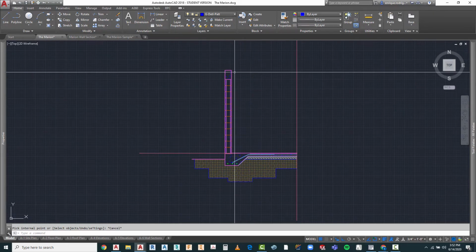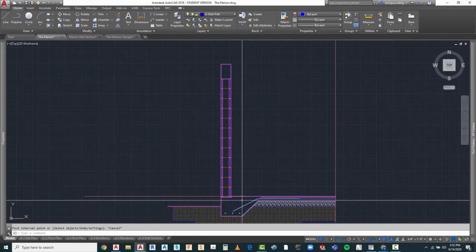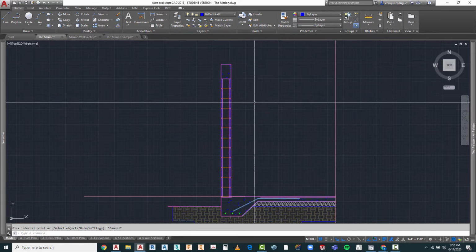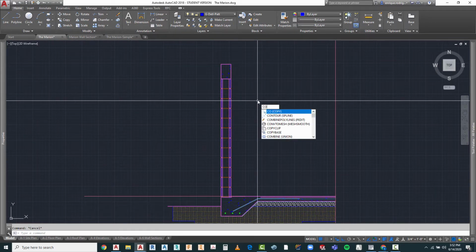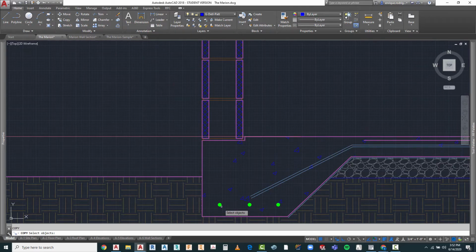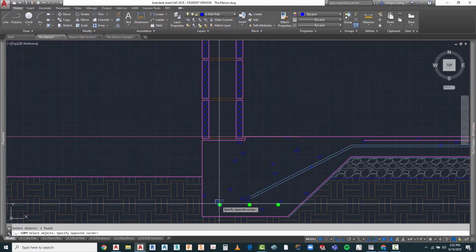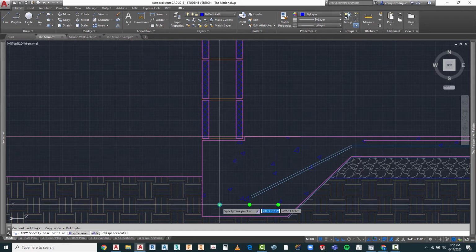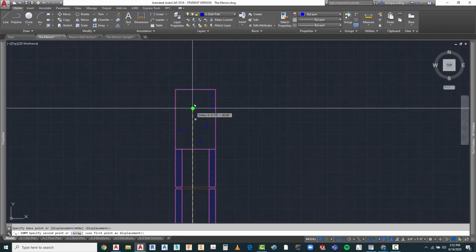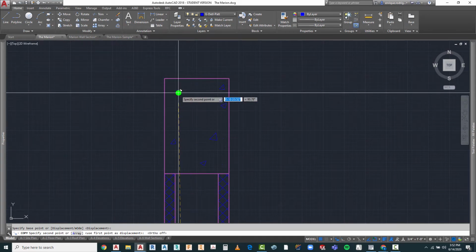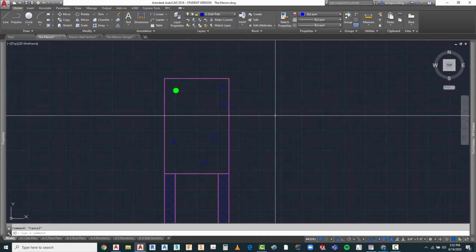So just like this concrete here, this concrete in here needs to be strengthened in tension. So we are also going to take our rebars and bring them on up. We're going to put 4 reinforcing bars in here.